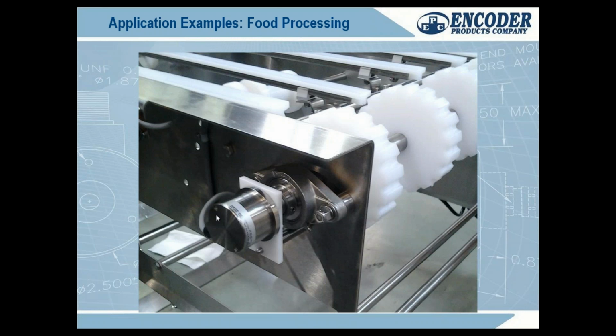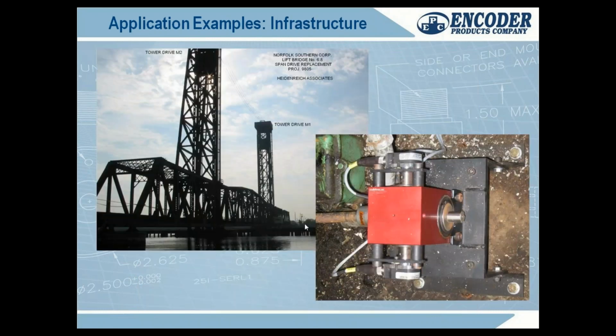Try and get an encoder that's got a covered rear end so that it's just totally enclosed. You can get what are called hollow bore encoders, which another way to say that is blind hole. There's not a hole all the way through. That's still a great way to couple on a shaft where the rear of the encoder is totally enclosed and not going to get sprayed on.